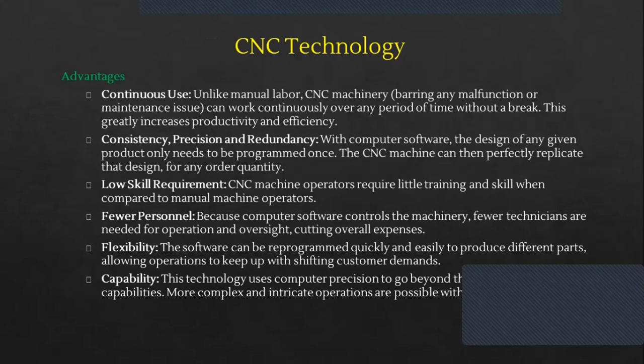The machine is not functioning properly. There are backlashes, right? The machine slides, okay, there's some gap in between tool post and the slide, for example, one example. So all of that will give rise to some defects in the product, so you will not get precise products, right? So precision and repeatability, so you will not have much wastage, okay? What you are trying to get is based out of optimal parameters that we have set.